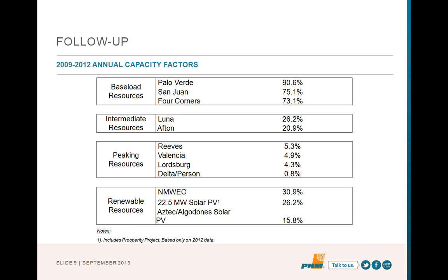Chuck, you had a question. Do you assign capacity values to these different resources? Yeah, the question is about capacity values. That's a concept that kind of shakes out in the model. What we assign for the resources is what it costs to build, what it costs to operate in terms of keeping it in good repair and fuel to operate it. And we also assign for things like a gas peaking plant what its capability is. If I turn it on, how many megawatts will it generate? So that's the type of information you give to the Strategist model.